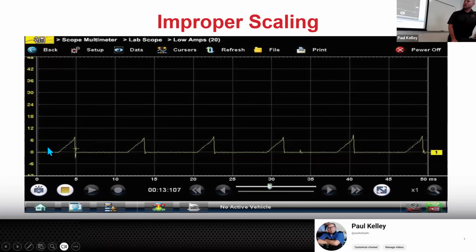All right. So if it's somewhere around 7 to 6, we could probably, rather than having our scale go from 0 to 42, we don't need to see up to 42. How about we make the scale 0 to 12, right? And then this would be a lot taller and you could see it in a lot more detail. Would that be fair? You can adjust your voltage range 0 to 12, not 0 to 46 or 48 or 42 or whatever. Cool? That'd be one way to measure it.